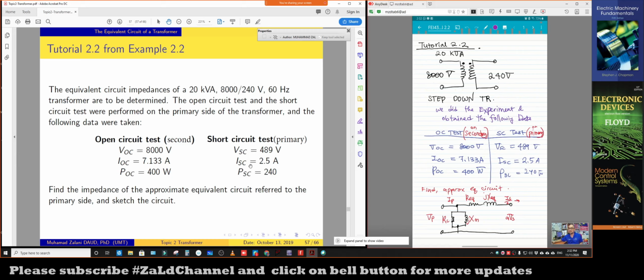In the short circuit test, basically we supply low voltage, but we adjust the voltage so that the current value is the same as the transformer's rating. That is why it is not the same as 240, because we actually adjust the current. We manually adjust it to make sure that the current supplied is the same as the rated current of the transformer.